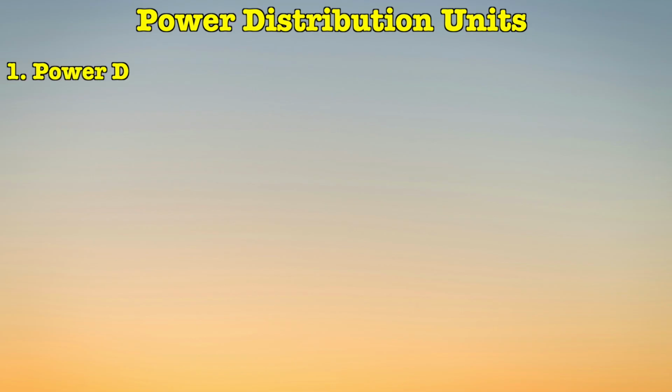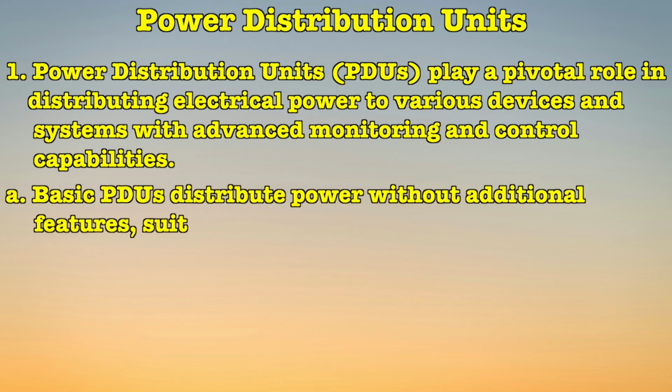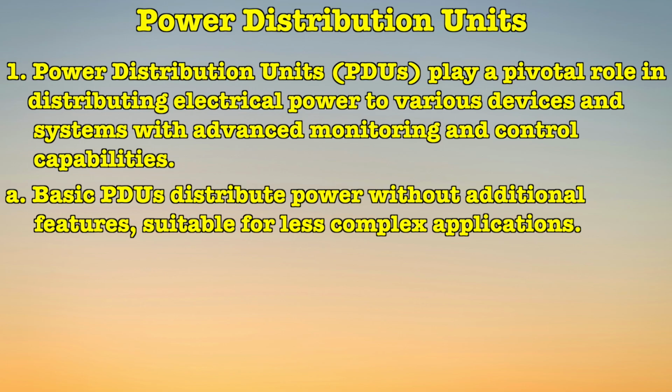Now let's talk about the PDUs, that is power distribution units, which play a pivotal role in distributing electrical power to various devices and systems with advanced monitoring and control capabilities. Under this, basic PDUs distribute power without additional features, suitable for less complex applications.